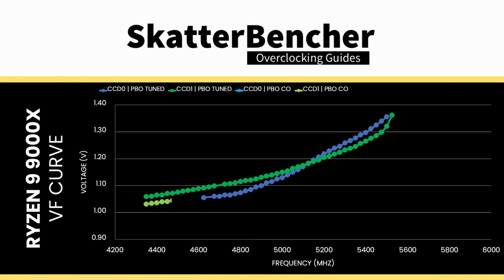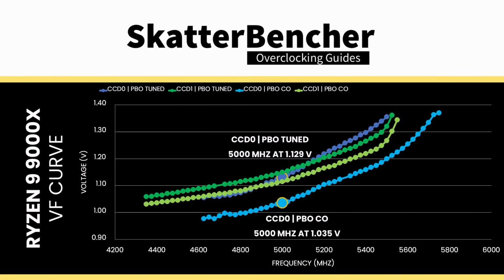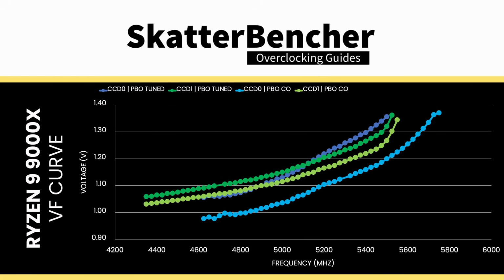If we set a negative curve optimizer, we can shift the entire voltage frequency curve along the voltage axis, and suddenly we need a lot less voltage for every operating frequency. For example, at default, for 5 GHz, CCD0 needed about 1.129 volt. However, with a -30 curve optimizer for CCD0, we now only need 1.035 volt. The same applies to the other CCD.